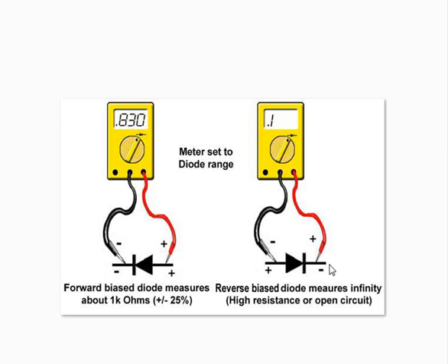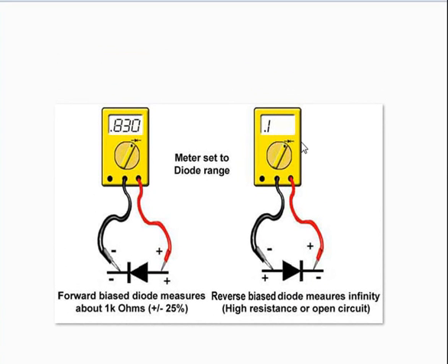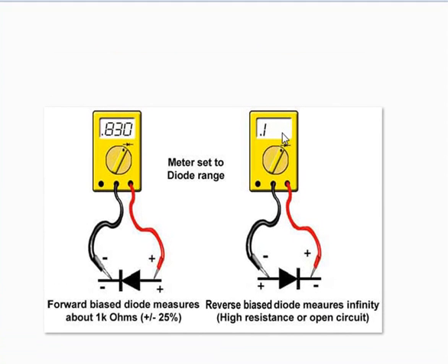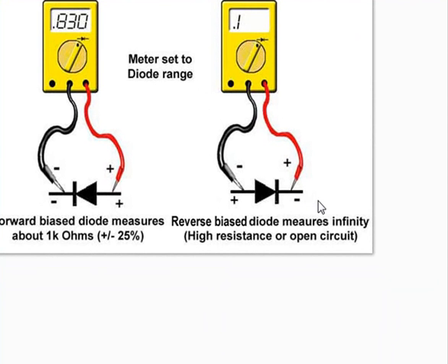What you have to see is that if you expose it to some light, more light, the reading will fall here. And if you block the light by your finger or your hand or anything, the value here will increase. That means resistance will increase. We are measuring in the resistance mode, not the diode mode which is shown here. In that resistance mode, once you block the light, it will show higher resistance, and if you allow the light to fall on it, it will show low resistance.